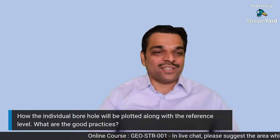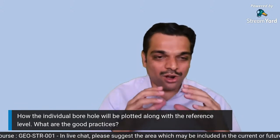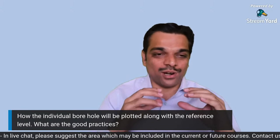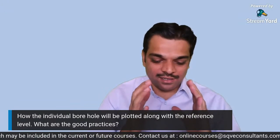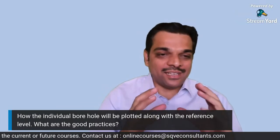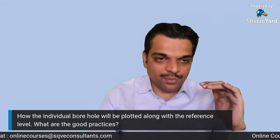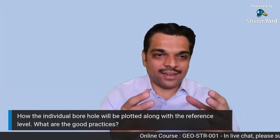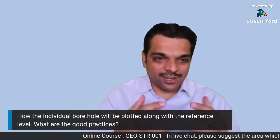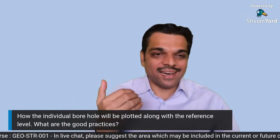Okay, this is the question which we have received. How should the individual borehole be plotted along with the reference level, and what are the good practices? I have seen that generally, whenever soil exploration is happening, the bore logs are taken from the existing ground level, and at that time cutting and filling might not have been done, because sometimes geotechnical investigation is processed at a very early stage.